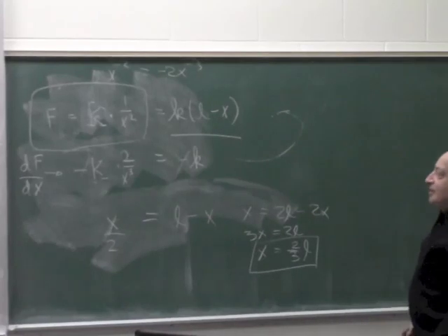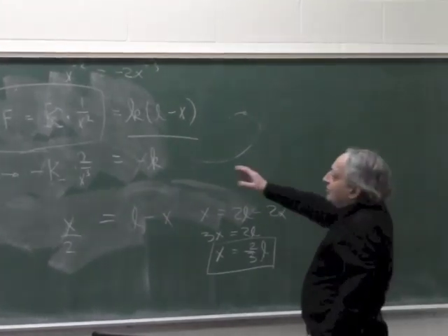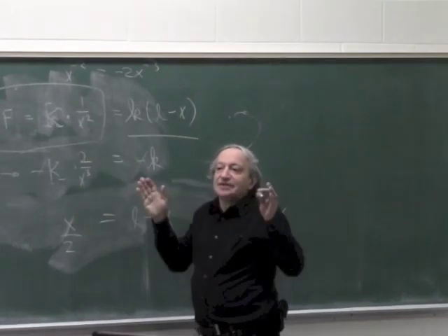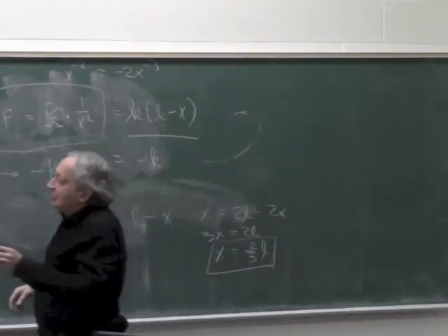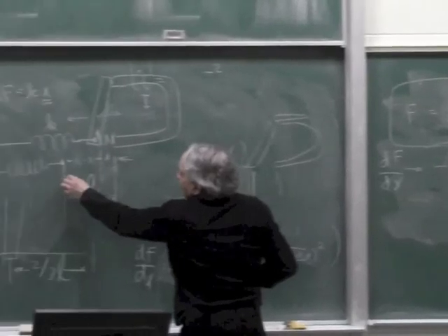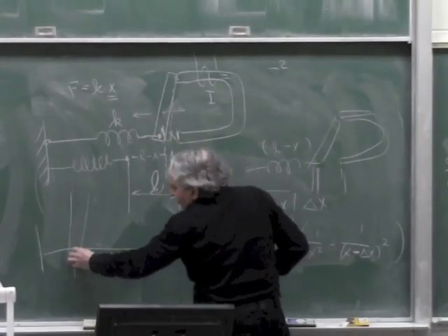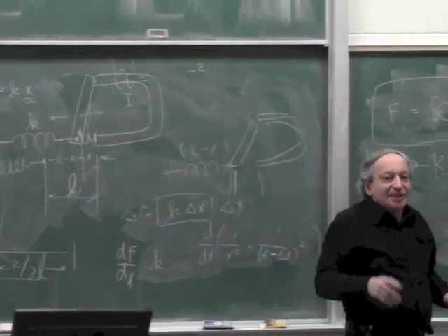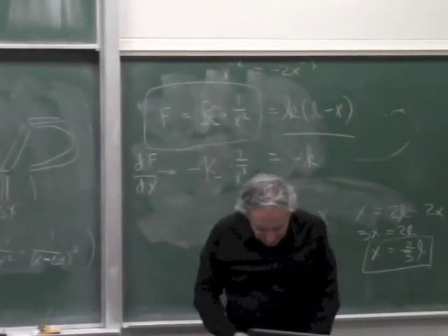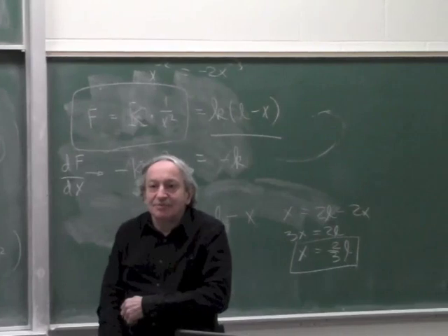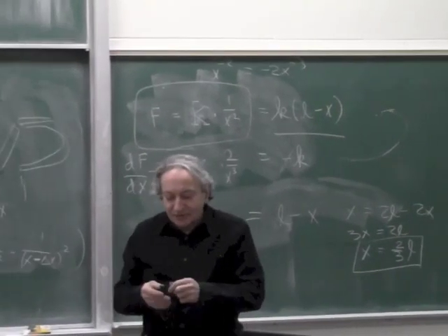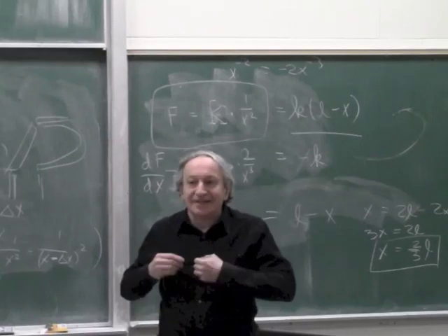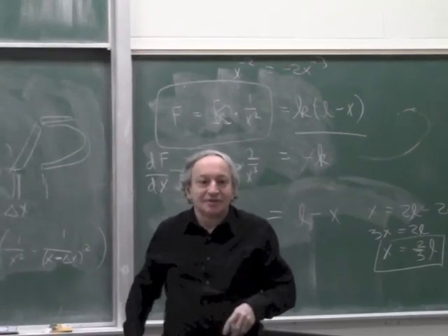So bottom line is, for any actuator which is inverse square law, you can only use 1/3 of the travel. Because for the first third it seems to work, and once x is 2/3, it snaps. So basically that means these actuators are not very good for servo, because you can only use 1/3 of the potential range.